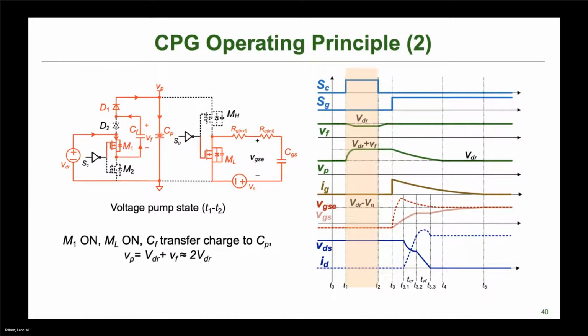Again, we've charged these up, transfer a little bit more charge from this one to this one, try to get this one pumped up as high as we can. Basically, this circuit is allowing this voltage here to be almost equal to twice this voltage here. So we're able to get quite a bit higher voltage here than what we have from just our power supply, almost double.